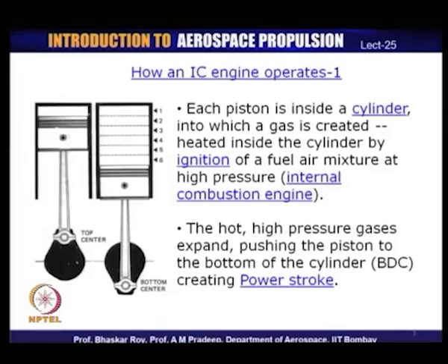Now, what we see here is a piston which is enclosed within a cylinder, and as the ignition occurs, the fuel air mixture is burnt and a high pressure is created at the top of the cylinder over here, and that high pressure then activates the piston. So, this movement of the piston is created by the hot gas, and that creates what we have already called the power stroke. It moves the piston from the top of this station to the bottom, which we have called the top dead center and the bottom dead center.